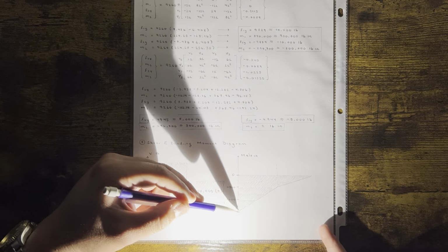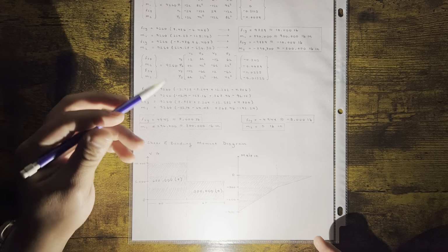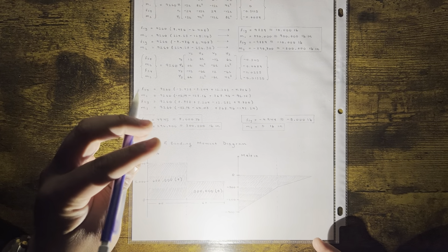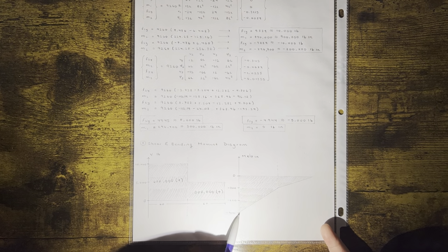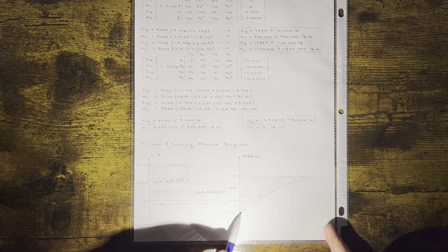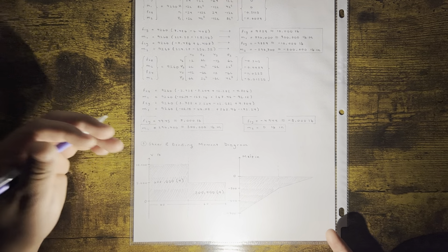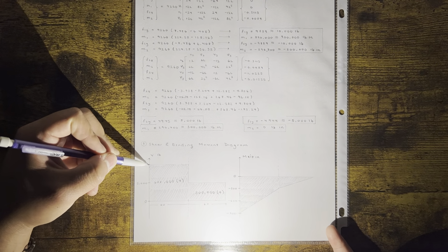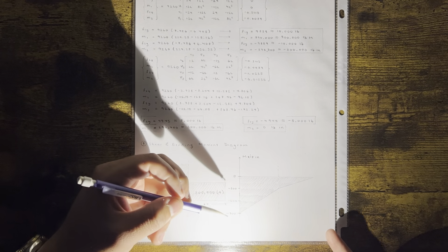But the reason you'd want to calculate the shear and bending is, once you know what your bending is, you're able to find the MC over I. Sigma is equal to MC over I, and you're able to check that allowable. So you calculate margins of safety. In this case, my max bending moment is -900,000. I have to make sure that my material can withstand that much load. It could be cyclic load, it could just be static load, whatever the case is. You do these problems to make sure that your cross-section can withstand this much shear, 10,000 in this case, and this much bending moment, -900,000. So that's pretty much it.